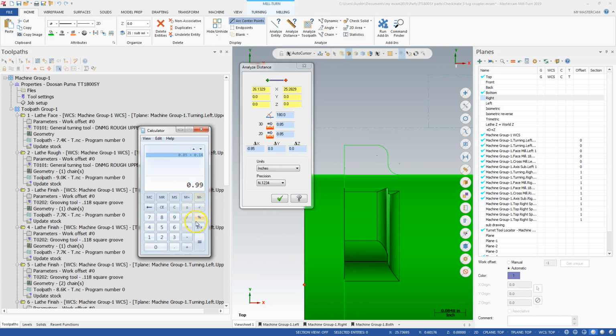And so my grip was 509 thou and 2/10. So I subtract that value. Then I need to pull this positive amount. So my B-axis move is going to go to positive 0.4808, and that'll put me in position to part the part at 20 in front of the face of the next part.